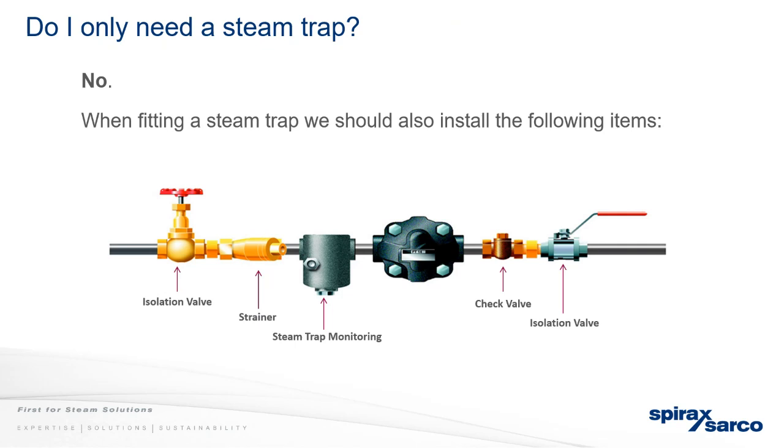When the pressure downstream is higher or equal to the pressure upstream, the motive steam connection kicks in by seeing the ball float has raised to a certain level, so it changes over mechanically. That then floods the compartment with steam, builds pressure, and clears the trap. So we do, as I said, have the APT, the automatic pump trap, or the MFP, our mechanical pump trap.